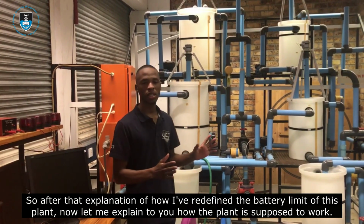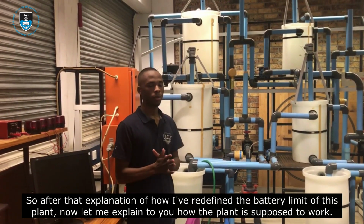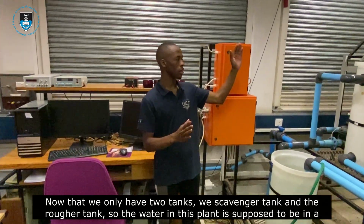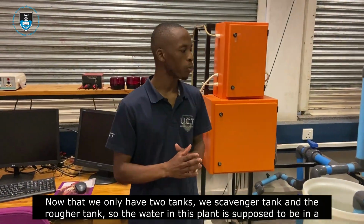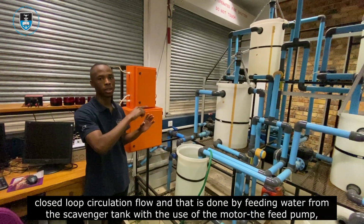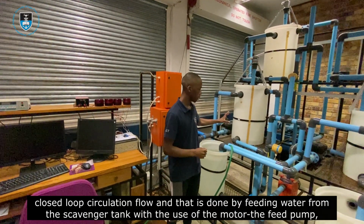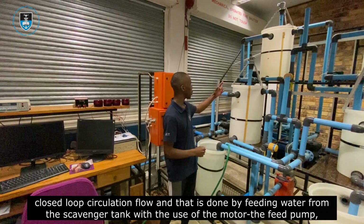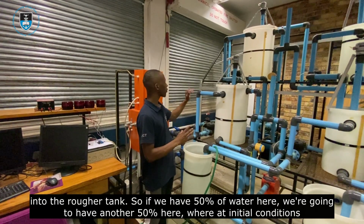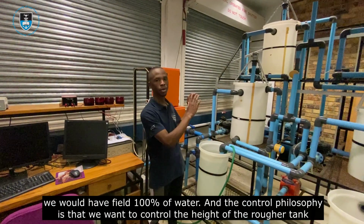So after the explanation of how I redefined the battery limit of this plant, now let me explain how the plant is supposed to work. Now that we only have 2 tanks, the scavenger tank and the rougher tank, the water in this plant is supposed to be in a closed loop circulation flow. And that is done by feeding water from the scavenger tank with the use of the motor, the feed pump, into the rougher tank. So if we have 50% of water here, we're going to have another 50% of water here, where at initial conditions we would have filled 100% of water.